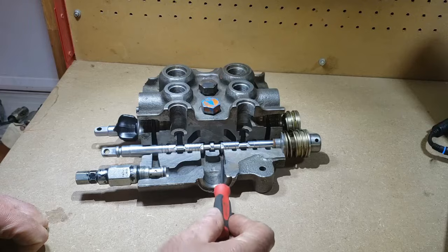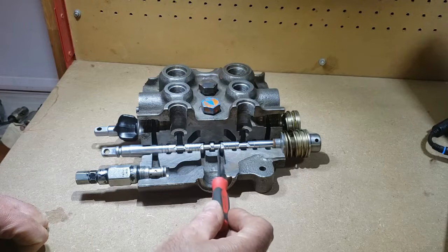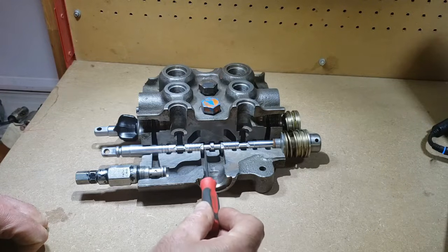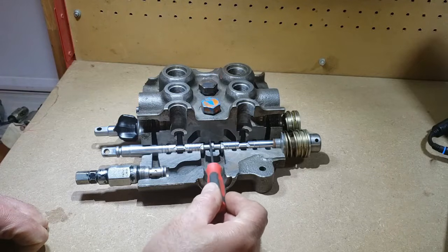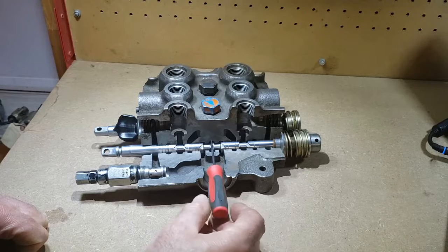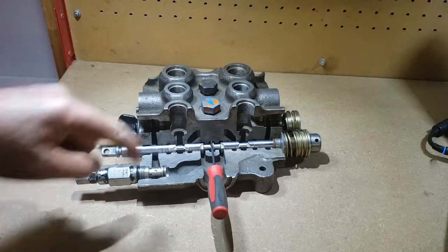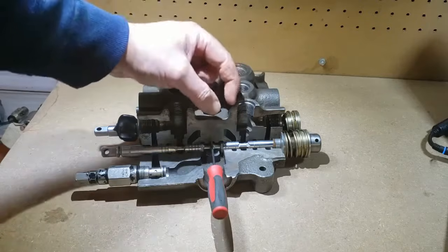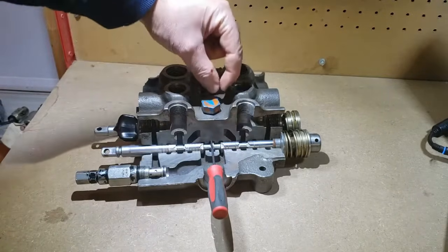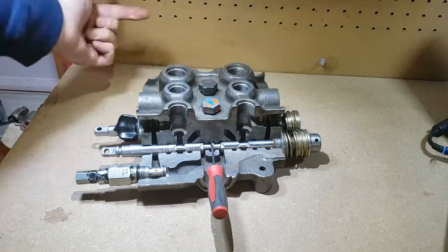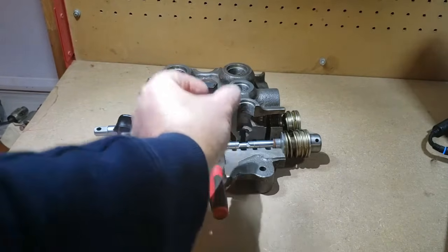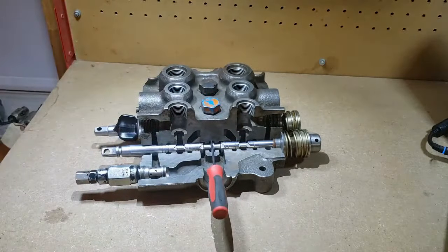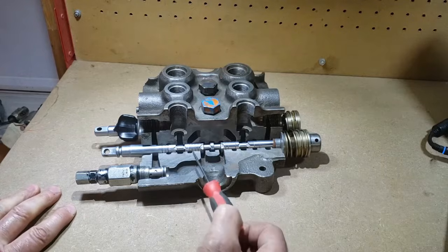Oil comes in, goes here through this clearance or this notch. It also goes through this clearance or notch and then clears the center land here and goes where I'm putting the seal pick. That's how the open center continues on to the tilt function. It does the same thing, wraps around it, and then around the auxiliary function, and then out the return. So the open center flow path, the oil has to do a little bit of a labyrinth kind of bending around each spool, but oil's pretty flexible, so it does that just fine.